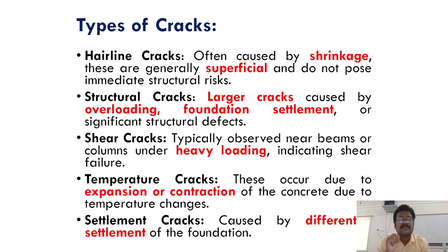Then the second one is structural cracks. If a crack is very long, it is called a structural crack. It happens because of overloading. It happens because of foundation settlement. So, as a civil engineer, we must look into structural cracks immediately.